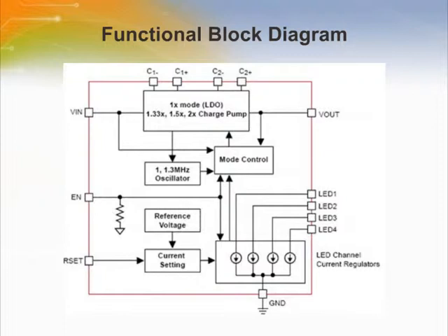This slide shows the functional block diagram of the CAT3604V. The device is an integrated quad-mode charge pump, which delivers the high efficiency levels normally associated with inductor-based LED drivers, while eliminating the associated high-profile inductors and unwanted EMI. The 4-channel charge pump has a pulse width modulating dimming interface and channel diagnostics, which include automatic detection for both short and open LED channel conditions to ensure the device maintains the highest efficiency level in all operating modes.